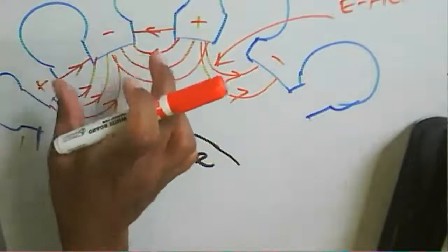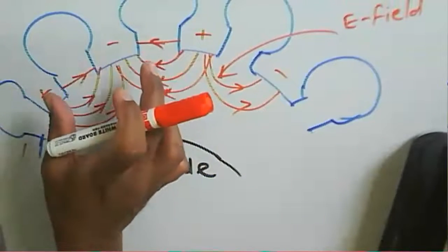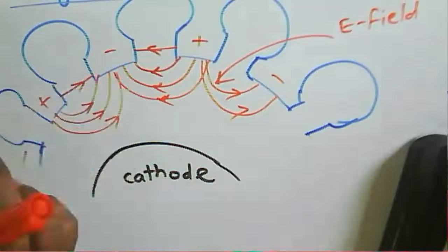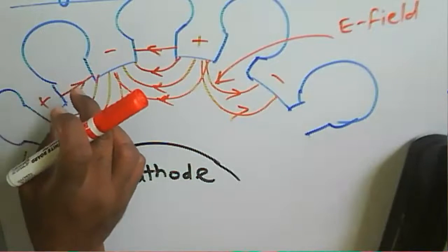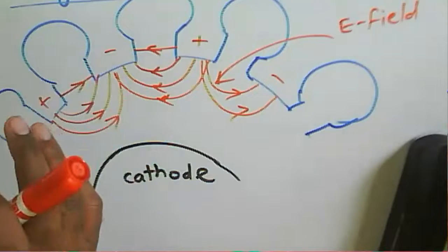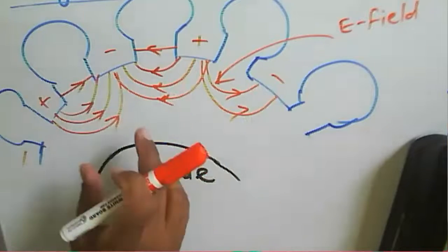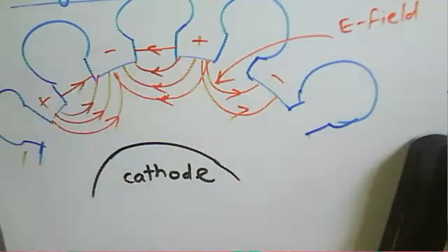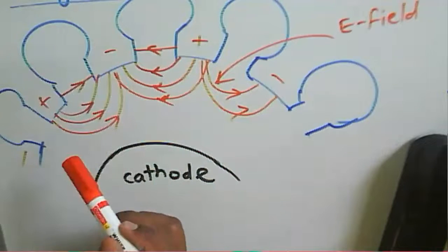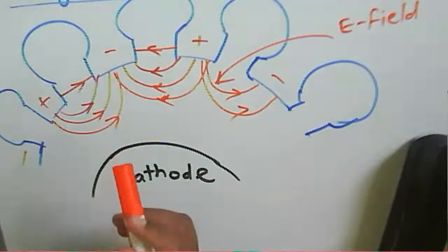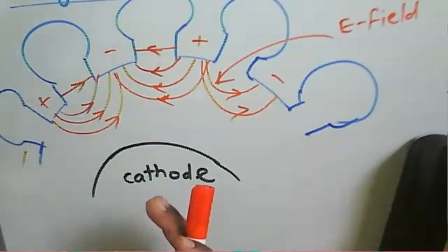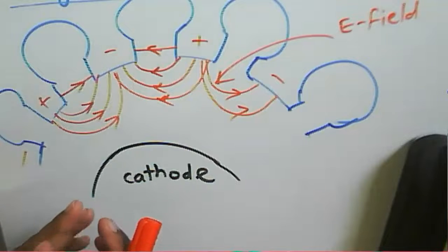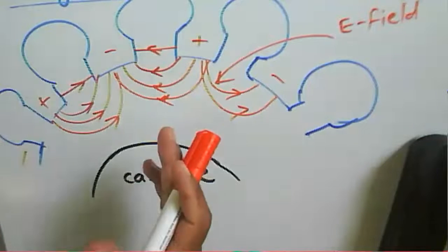Whatever cavities we are using have a high Q, so the resonant frequency of the cavities and the frequency generated through this magnetron circuit will be similar. Generally we consider it a similar one. Now, what will be the microwave frequency? That is about the generation of microwaves, in the gigahertz range, but the frequency depends on the interaction region we have.